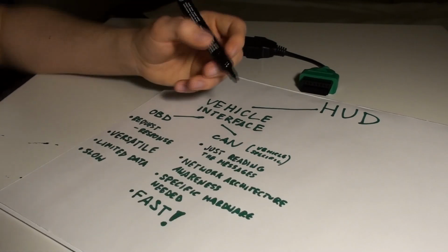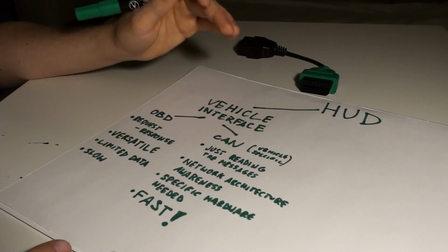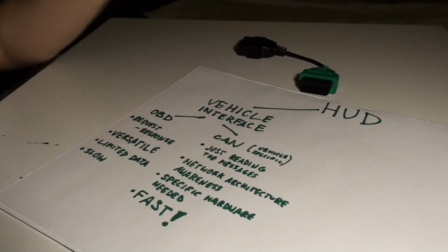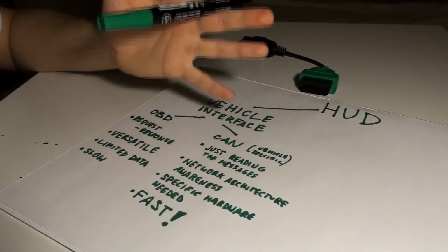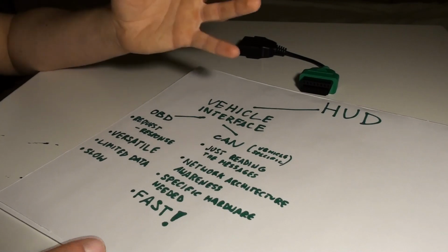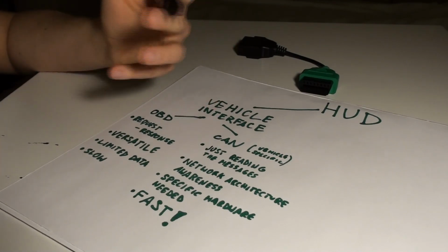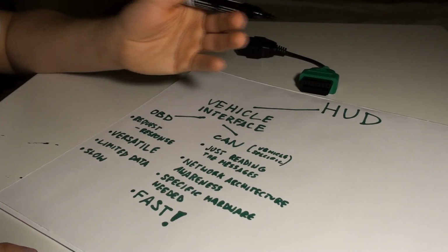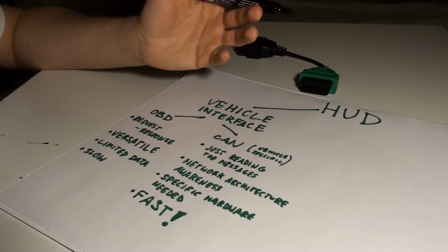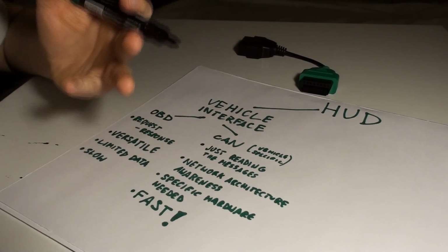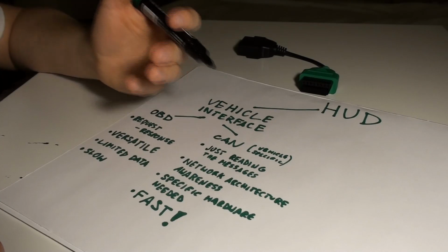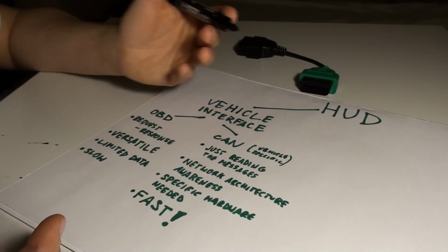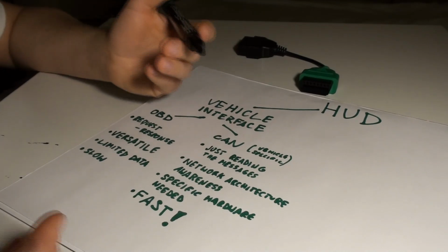Okay, and there's this second approach, the vehicle-specific approach, where you want to solely read the messages from the bus, the messages that contain the information that you want to display, just like it's done by the instrument cluster and so on. So to do this, you actually need to be aware of the network architecture that is present in your vehicle, and what data buses are implemented there, and based on that you need specific hardware to act like an ECU that is already present in the car.